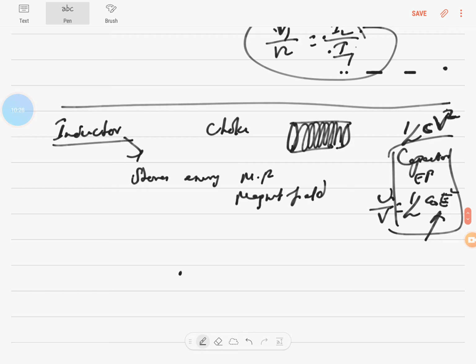So when you are switching on and off the switch, the current changes from 5 amps to 0 amps and 0 to 5 amps. At that time, the tube light needs a steady current. It will not accept this increase and decrease of current. So what happens is, at that time the inductor supplies the energy. That's the purpose of the inductor.